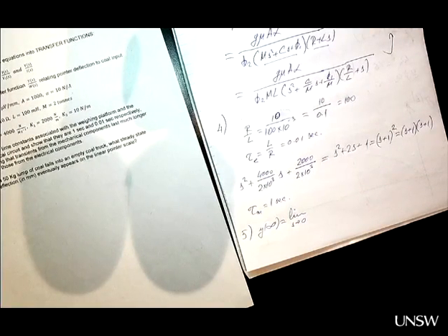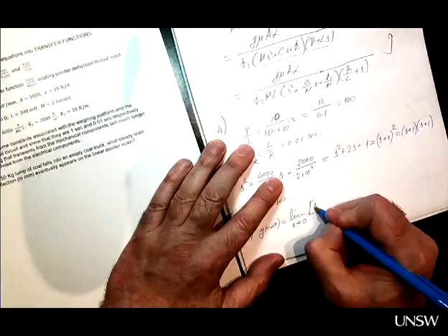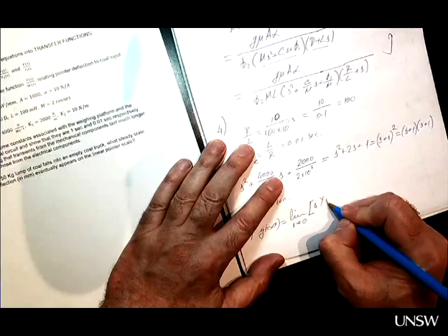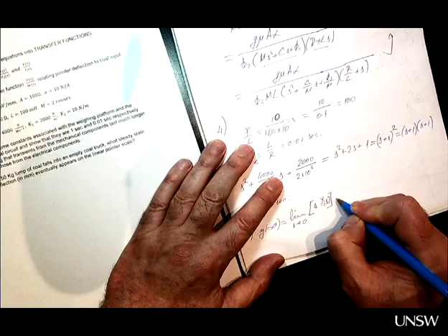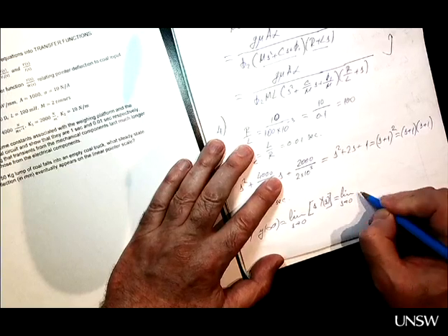So the whole problem, as complex as it looks, doesn't require inverse Laplace transforms, partial fractions, or tables. So it's just the limit of s times y of s, which is equal to the limit as s approaches 0 of s times input times transfer function.